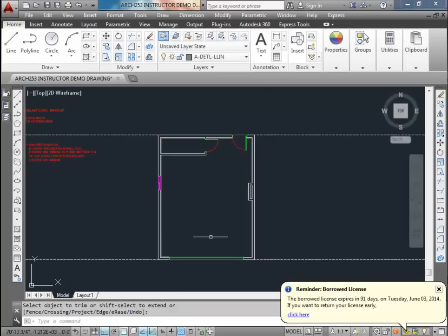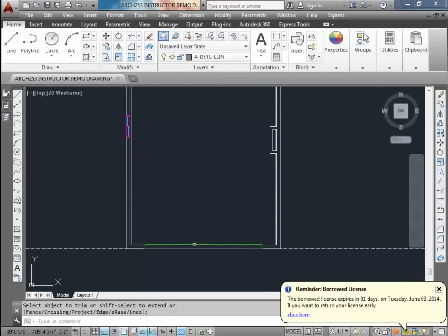Now that we have our garage drawn, this garage door, because it's a sectional door, when it opens up, is going to take up a little bit of space in the roof, sort of above where the cars would park. And we should probably show that in the plan. The reason is that we want to make sure that we don't place anything in the line of where the garage door needs to come up. Otherwise, the garage door won't open. So a lot of times it's handy to put in a dotted line which represents the full opening of that door.